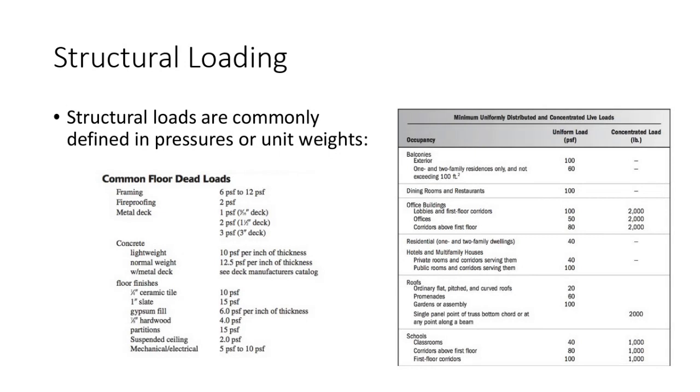And I'll admit, I am glossing over a lot of details that we'll probably talk about in our design courses, like load factoring and live load reduction and some other stuff that'll become important next semester. But for right now, I want you to understand the general concept. Any questions about the loads itself, how we're speccing them out? Again, we tend to spec them out in terms of pressure, like pounds per square foot. Any questions on this?